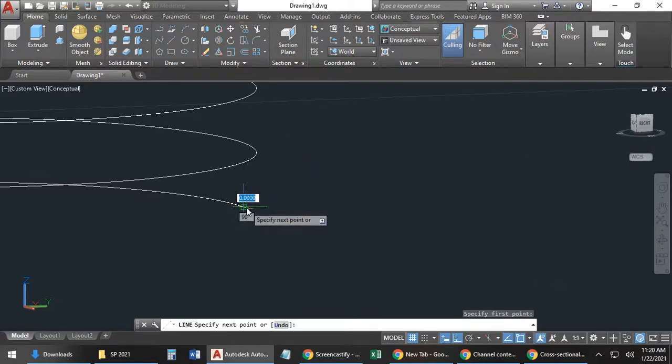So again, like I said, if I were to go up from one height to the next for the turns, that distance would be the 1 inch divided by 20 threads per inch gives us 0.05. I'm going to make that a little bit smaller. So if I type in 0.0, I don't know, 49, okay, that'll be just a little bit shorter. In this case, the thread coming out, you can get close with that thread coming out.